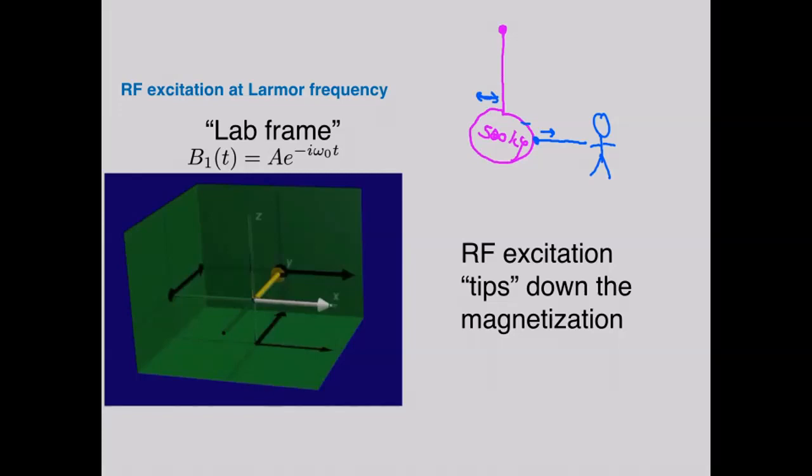So what you're going to do every time the mass is going towards you, you pull a little bit, apply force. And when it goes back, you don't apply any force. When it comes towards you, you apply a little bit of force. Because you only apply the force when the mass is coming to you, you can move this 500 kilogram mass quite a bit with this really tiny refrigerator magnet. This is what's called resonance, because you're applying this force exactly at the natural frequency that this mass is oscillating at.